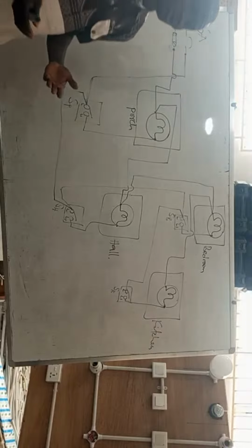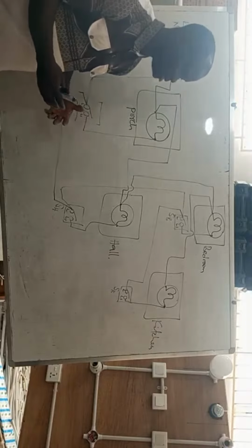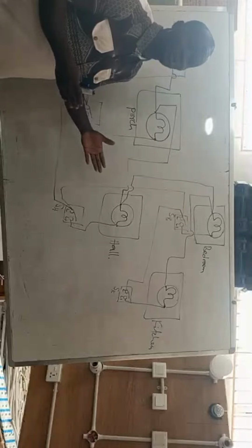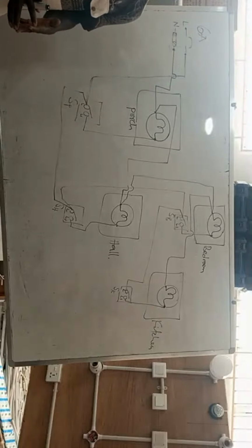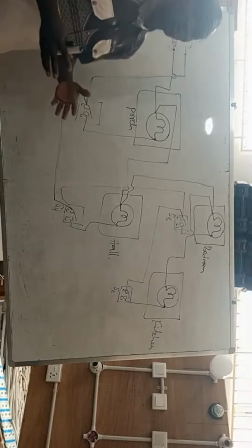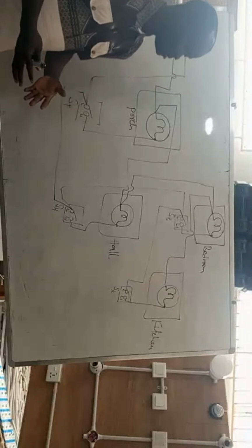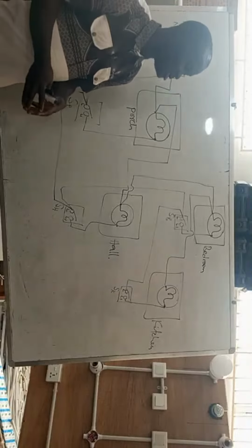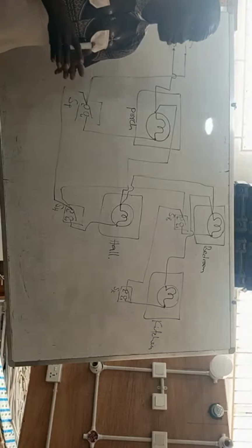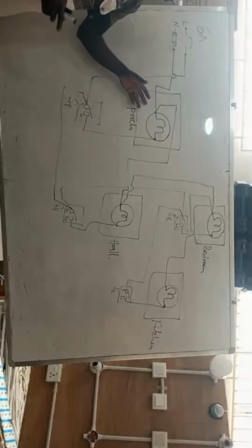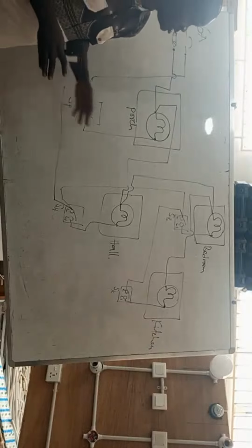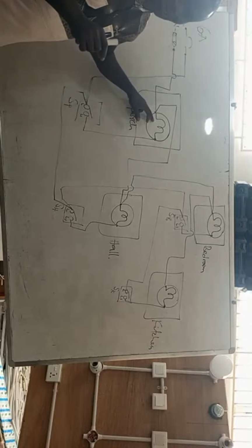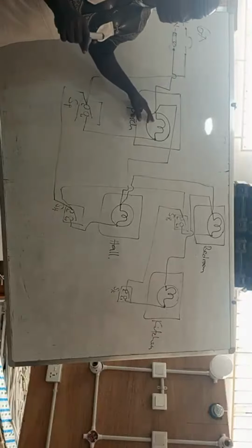But it is possible that later on, the lamps you are fixing may be replaced with other lamps that come with metal parts. That is why it is important that whether you are using luminaires that have metal parts in the first place or not, you should provide earthing wires or earth cables at the lighting point anytime you are doing your wiring.